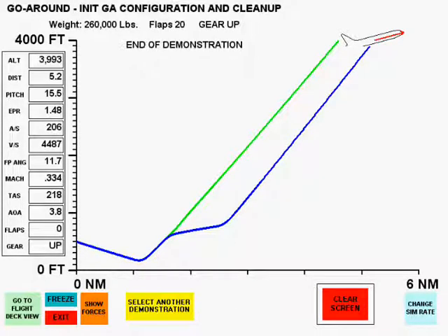Now, let's sum up our observations of jet aircraft climbs. The basic rule for jet climbs is to use existing speed to clear obstacles. Then immediately accelerate to the best rate of climb, best economy, or cruise airspeed, and clean configuration.